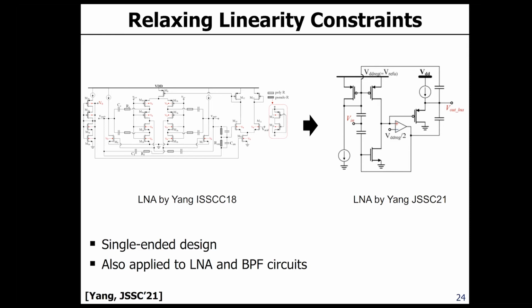It requires a lot of tweaking and careful architecture work to ensure that this whole circuit operates at 0.6 volt, which is fairly low for an analog circuit. We have almost a 5-stack here, and some of them are definitely in the triode region. So you'll be surprised, and maybe a little bit scared, I guess. These are fairly delicate, complicated designs.